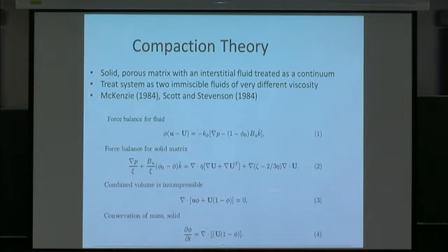Now there's different ways of doing this depending on whether you break up the pressure in different ways. I've just left the pressure as just the liquid pressure. Okay, so then in terms of mass conservation, you've just got that the combined volume is incompressible. And then the evolution equation comes from the conservation of the solid phase.